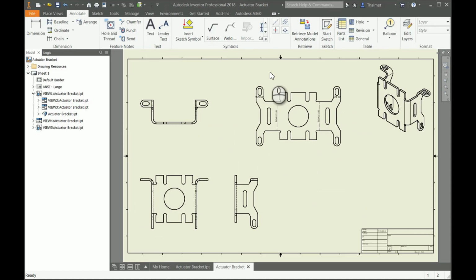And like I said, we're doing this in Inventor. The same concepts are going to apply if we use any other type of solid modeling program. We always want to make sure that we have the sheet metal default set up first and then get into creating our product. Once we're done with the product, we want to make sure that we create that flat pattern. That way we can use it inside of our drawings.